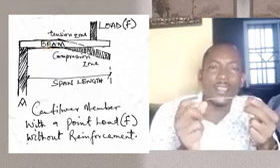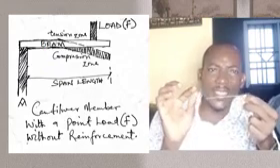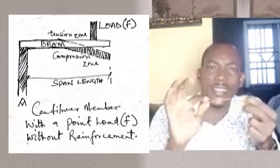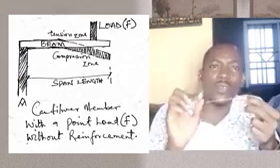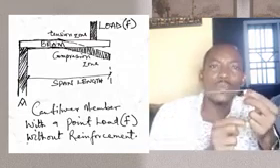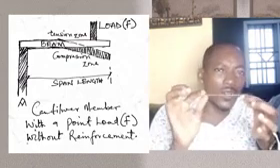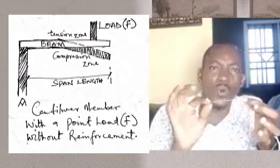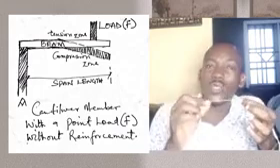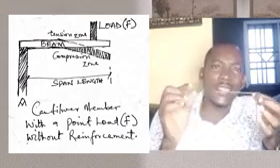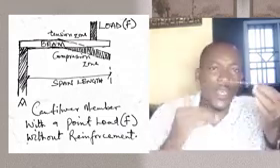All right, so if you watch closely, something like this at the side, depending on the span, when I use the word span, I'm talking about the length from this pillar here, which is the column position, to the end of the beam. If it is not much, you can put 3 there. If it is much, you can increase it. But the idea I want to get is where you place it. Is it going to be at the top or is it going to be at the bottom?